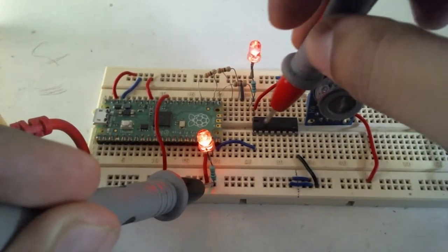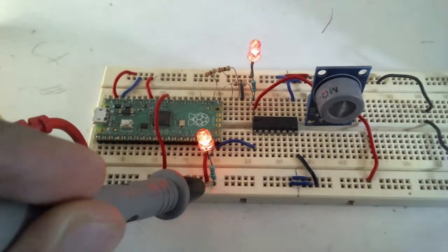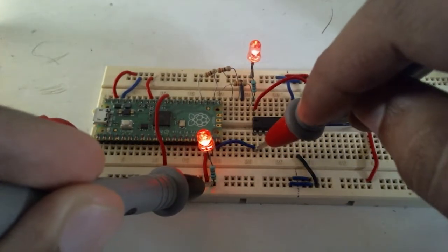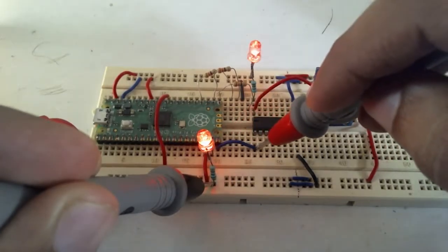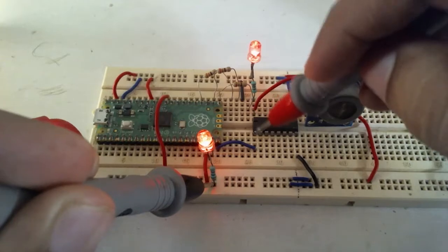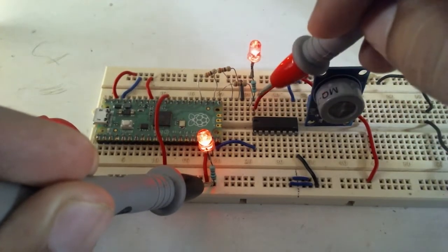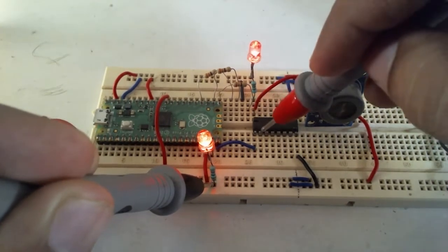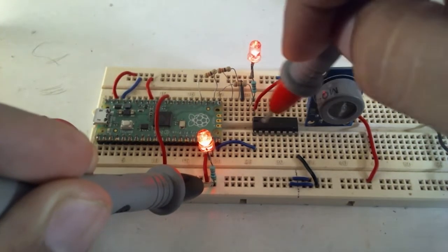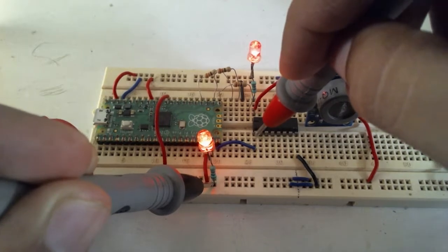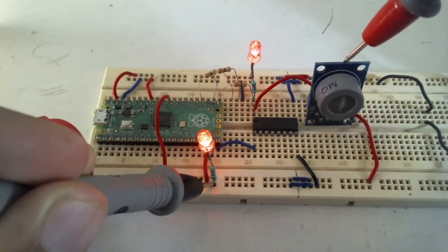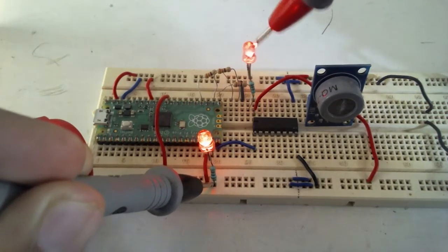This IC is an array of 7 BJT transistors, power BJT transistors, which will switch 5 volts as the input signal is applied to the base. So this is input 1 and this is output 1. This is input 2 and this is output 2. But I am not using the rest of 6 transistors. I am just using input 1 and output 1. So output 1 is connected to the heater coil of MQ7, also to one LED.